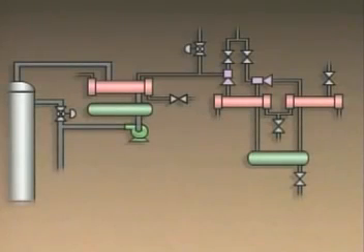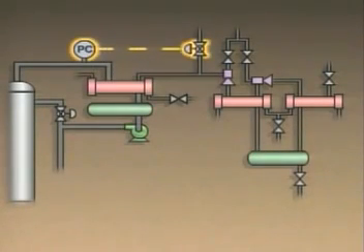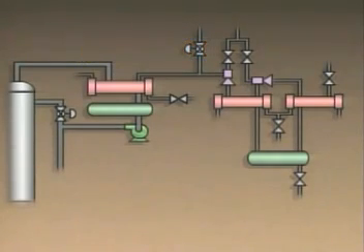The next step is to shut down the vacuum system. First, a pressure controller is used to open a bleed valve in the vacuum line to break the vacuum. Then the two steam jets are shut off in the reverse order from the startup sequence.